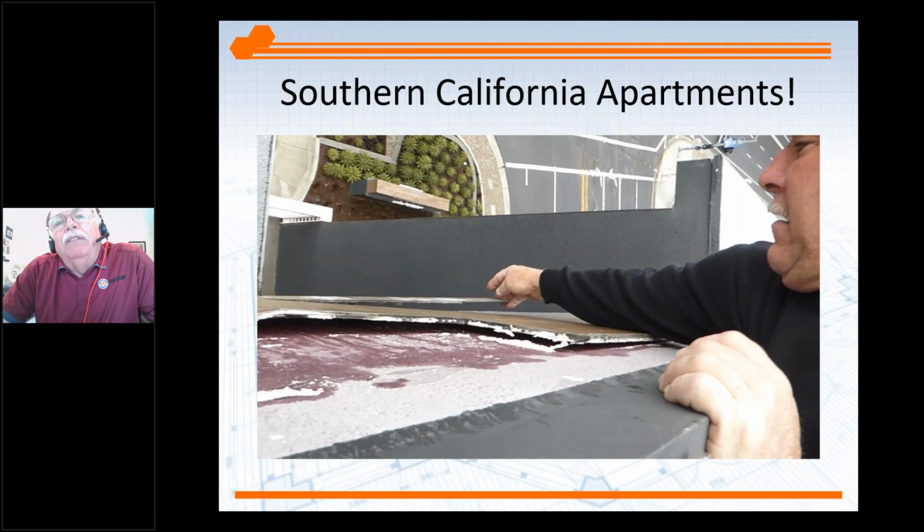And they also weren't getting excellent coverage. They used too small of a notch trowel. They didn't do any back buttering or what we call flat troweling on this installation. And they also didn't use proper movement joints. At the end of the slide show today, we'll be talking some about the movement joints and give you a little bit more details about that. So just about everything in the specifications, the details, was completely missed on this project. So the installers had to go back in and reinstall. We kept the architectural firm out of trouble because they had done everything properly.